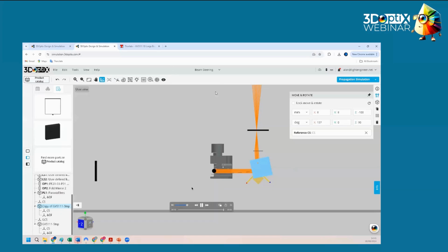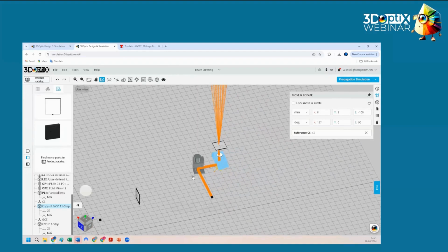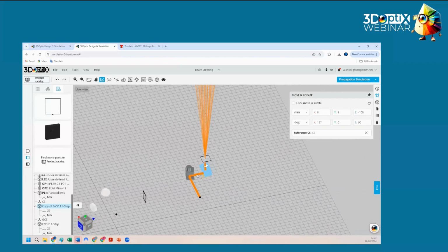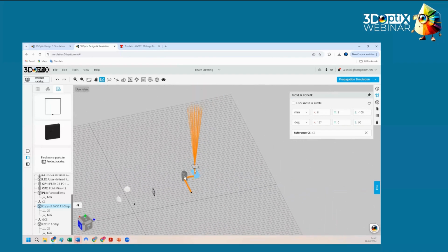That's our presentation for today. We went over a number of different positioning schemes, both with respect to the local coordinate system and with respect to an external coordinate system, snapping to the chief ray, which is a really nice feature. We went over a static steering system and a dynamic steering system, and you can see how you can bring in external elements from CAD, from the different optics catalogs, different lenses, and fully build up a system and simulate it before you order your parts. And that's our presentation for today. Thank you very much.